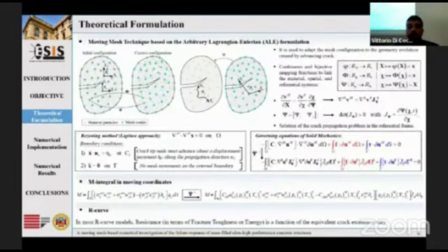So, besides the spatial and material systems, the moving mesh introduces a new mesh coordinate system according to which mesh nodes can move independently from material nodes. So the various frames are linked by proper mapping functions, which are needed to express all governing equations with respect to the mesh configuration. Moving mesh adopts the Laplace regularization approach for reducing mesh element distortion.